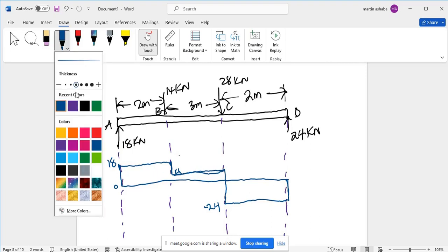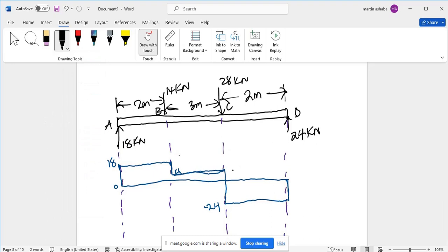One thing you have to note is that for these simple beams, if you're drawing the shear force diagram and it is not completing at 0, or maybe you have a negative 24 going upwards and stopping at the end of the beam, and when you go upwards you don't finish at 24, then you know there is a problem. Let us take an example. You have got a negative 24 here, and this other part is given, for example, as 30. Just know there is something wrong.